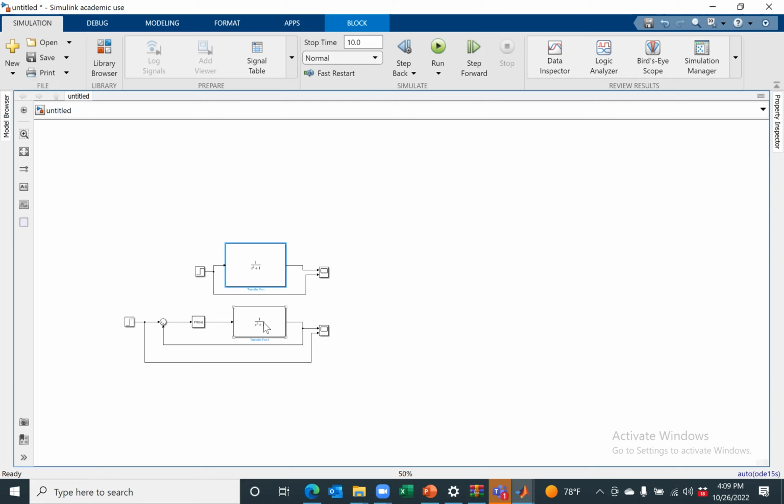You start walking and now you have this proportional control and you have the derivative term, which is dependent on the relative velocities or basically error dot. So what is the velocity in between? And then as velocity starts decreasing, you kind of start controlling that controller term. So you kind of go close. You don't overshoot, you kind of go close. But the problem here is because you have the velocity dependent controller, you are going to have some type of oscillations. Are you with me so far?